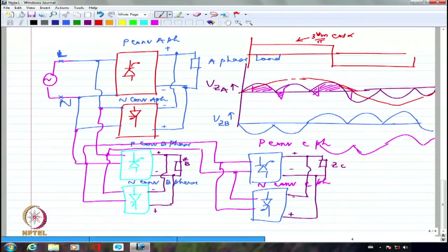Thyristor based converters will work slowly. They are much slower than IGBT or MOSFET or any of them. And they can handle single-handedly almost 30 megawatts of power without any difficulty. Because of which, for high power drives, we generally tend to prefer thyristors. And cycloconverters reduce the frequency.